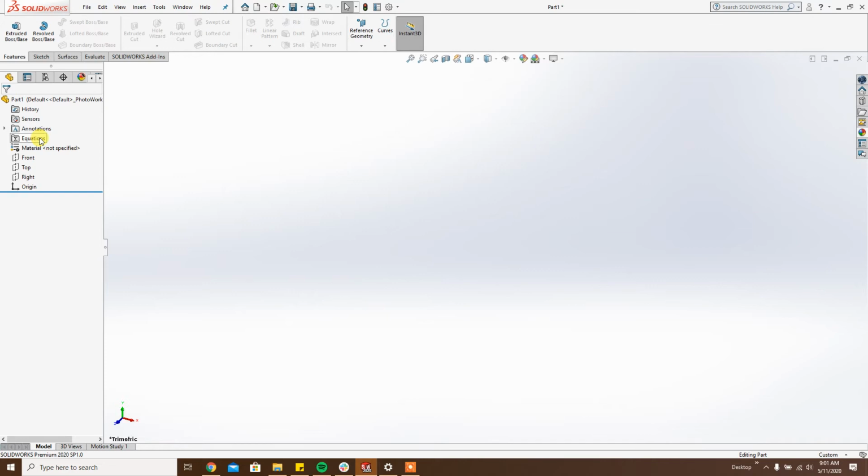Say, this length, I assigned this length, but after some time I can change the length and rebuild my design, my item, so I will not need to do it all over again. I will just rebuild in order to apply the changes everywhere I've put the equation, or I've defined a variable. This is what equations are for.